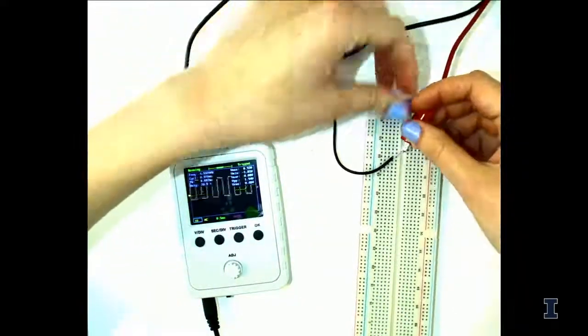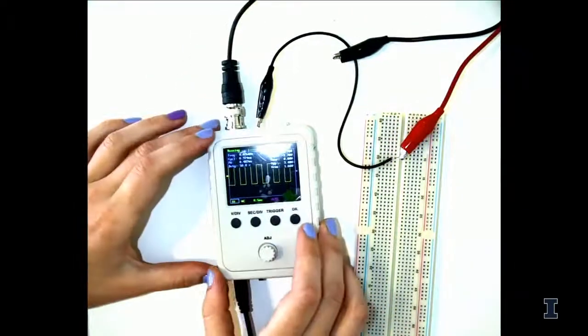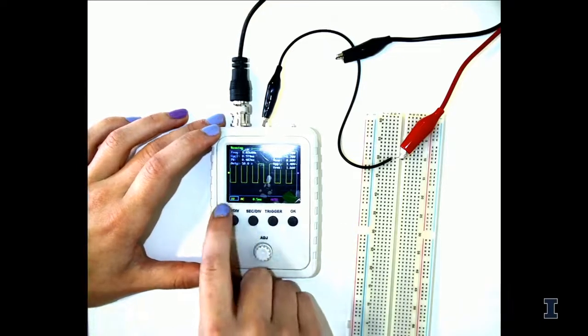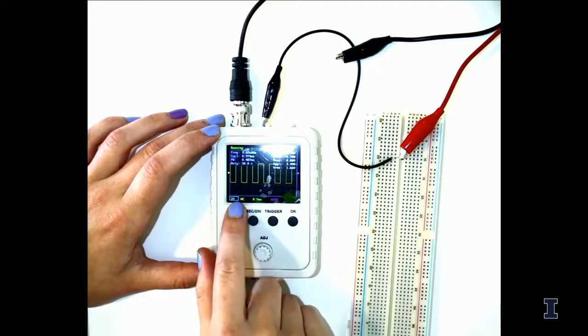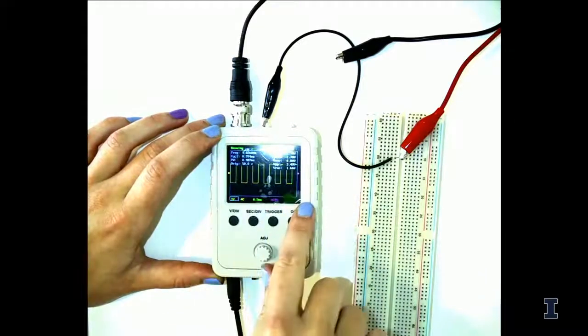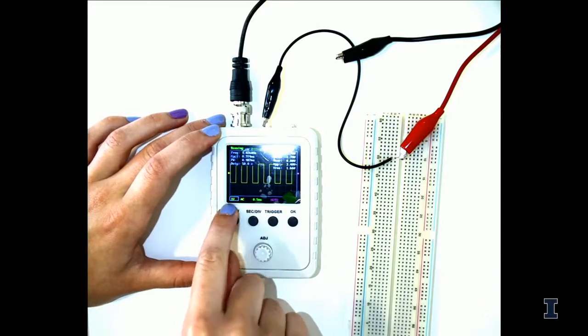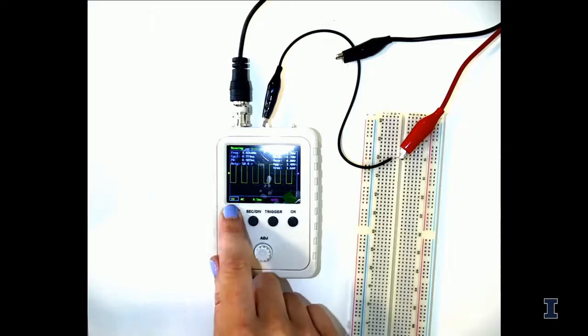Oh, okay. So we plug this in, you'll see a signal appears. And it's a 1 kilohertz signal, and we can tell that because at the bottom you can see what your measurement values are. The oscilloscope screen has a grid on it, and on the left we see 1 volt. That means that your Y increments are in 1 volt.